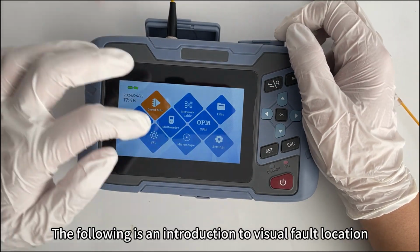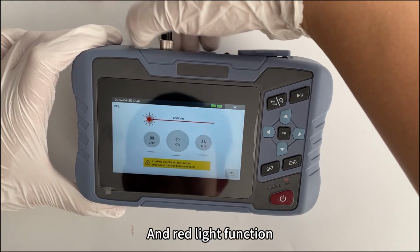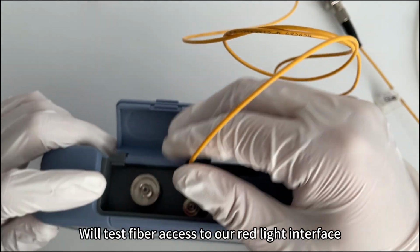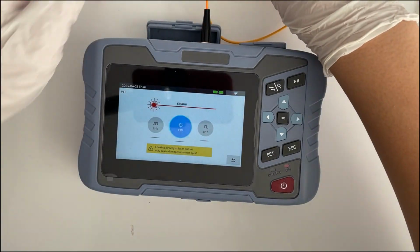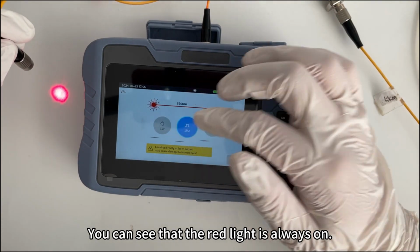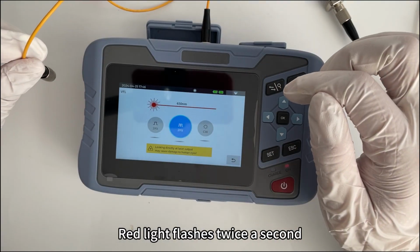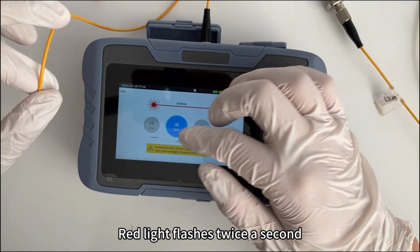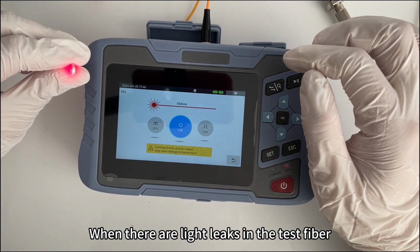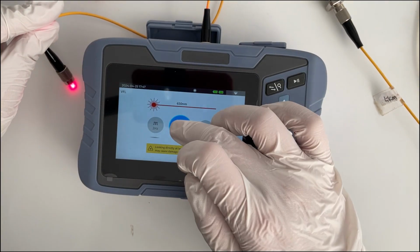The following is an introduction to visual fault location and red light function. We'll test fiber access to our red light interface. You can see that the red light is always on. The red light flashes once a second. Red light flashes twice a second. When there are light leaks in the test fiber, you can see that this is the light leakage point.